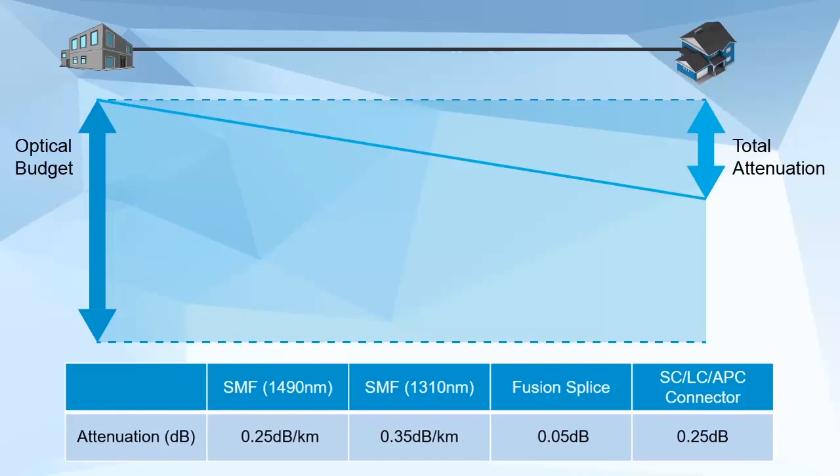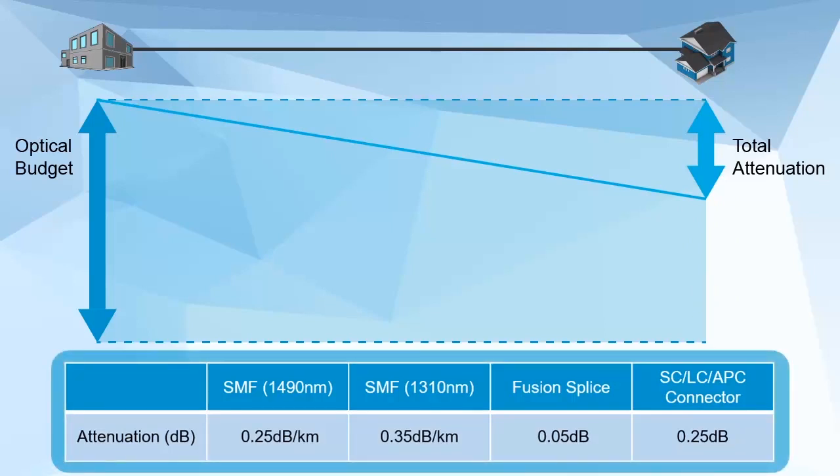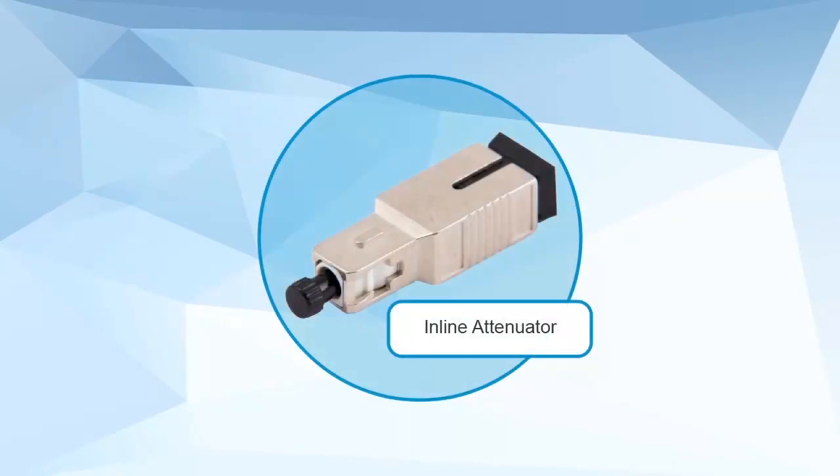In practice, the aim is generally to have attenuation as low as possible, because that means we can transmit further before the power of the output signal drops so low that the receiver can no longer detect it. This table provides information on the loss factors for fiber cables and connectors which must be accounted for, including upstream and downstream link pass. Note that the ONUs also have a maximum receive power.